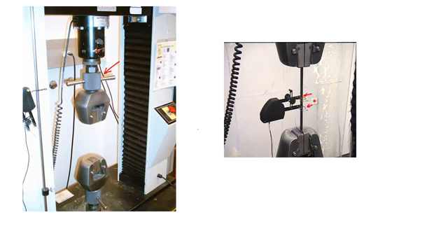And what the extensometer does is measure the deformation. Program it to divide by the original length between these two clips, and it'll give you a measure of the normal strain that's occurring within the specimen. And over here, there's a force transducer, and that force transducer measures the amount of force that the actuator is applying, and then you can calculate the stress by dividing by the area.